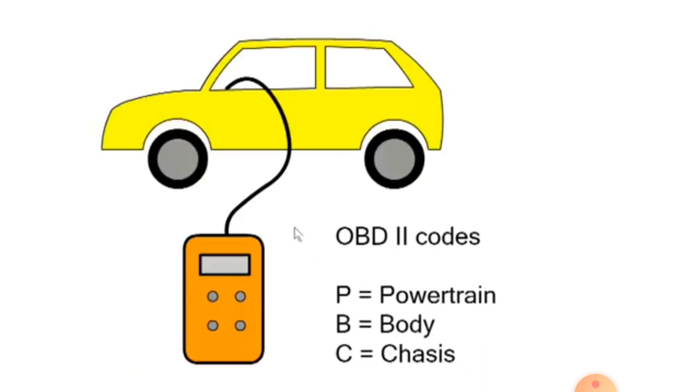The OBD2 standard, Onboard Diagnostics 2, allows code scanners or data loggers to communicate with the ECU. Fault history and fault codes can be downloaded to determine which sensors are not healthy. Caution must be exercised when using a fault scanner, as quite often when there is a faulty reading from a sensor, the source of the problem might be elsewhere in the system. Also, high-resistance electrical cable connections can lead to erroneous readings, so check everything and, as a last resort, change the sensor.